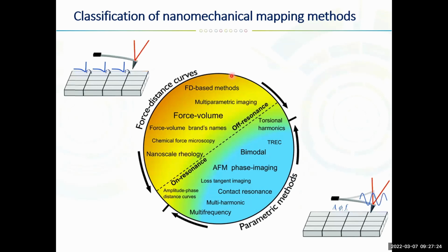Just keep these methods in mind when you talk about surfaces and interfaces. And for example, for low energy solids like polymers, we usually use contact angle measurements. It depends on the surface roughness.